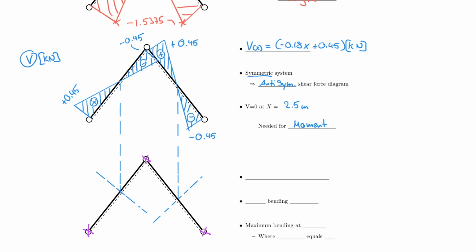And remember that snow is also attracted by gravity, just like the self-weight. And therefore, I don't have to change my logic of whether the beam is smiling or frowning. In fact, it's smiling. Therefore, I must end up with a maximum in the middle, and my moments are positive, positive, and positive right there.